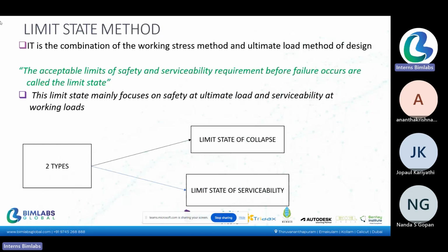Coming to the limit state method, as most of you are familiar with it, it is a combination of both the working stress and ultimate load methods of design. As I mentioned, the limit state mainly focuses on safety at ultimate load and serviceability at working loads.